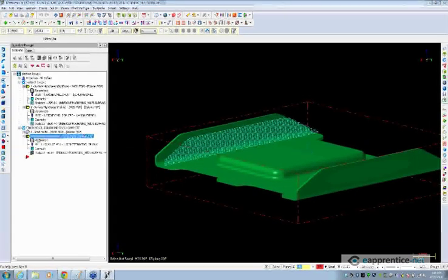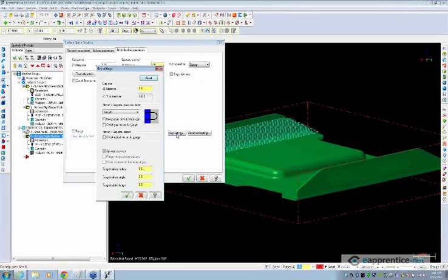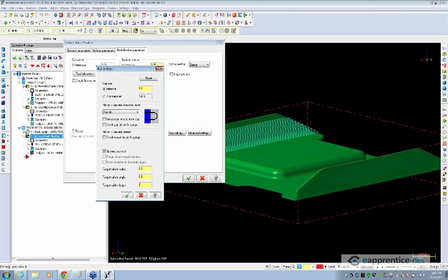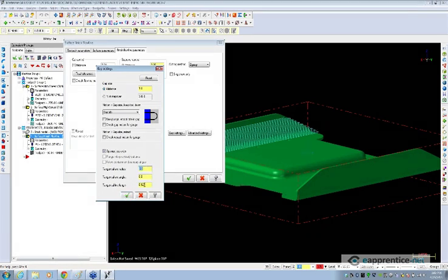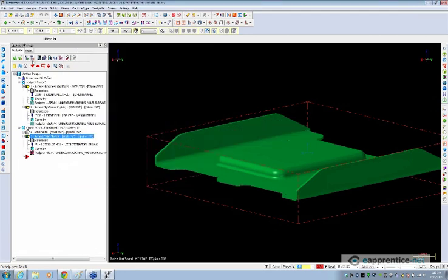Now at this point, with flowline, I can do a couple of things. If I go back into the gap settings, I can use these tangent options with smooth to extend the entry and exit motion off of the edge of the surfaces. So if I use a tangent line length of maybe 0.625, a tangent arc radius of 1 inch and a tangent arc angle of 45 degrees, we'll explain what this is in a second. And now I'll regenerate that.